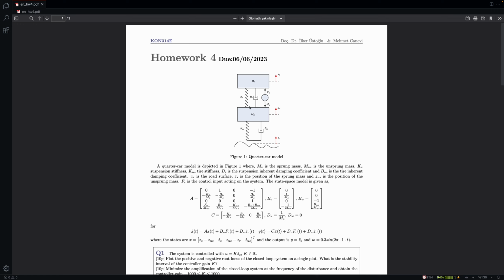And then, of course, we have the vehicle body. And when you as a driver sit in a vehicle or as a passenger, you are in the body and you will experience all the forces that will apply to the body here. And then again, we have here the suspension between the tire and the vehicle body. But again, the model is not that complicated. We have mass spring dampers for that.